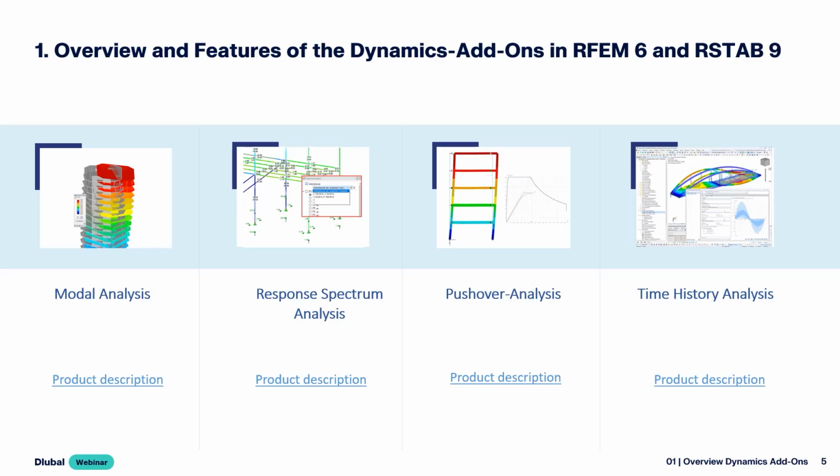And since we then know where we are at, we can also investigate what damage is estimated to be there and where it could be. So then we can decide where we should look to reinforce single columns or whatsoever, which we would have expected the damage to be at.